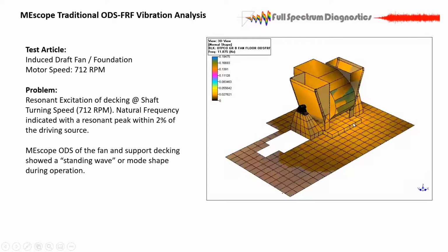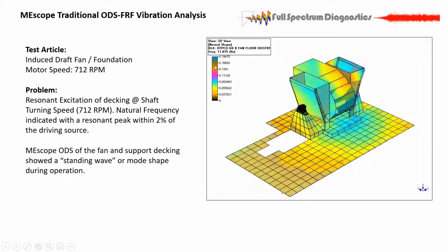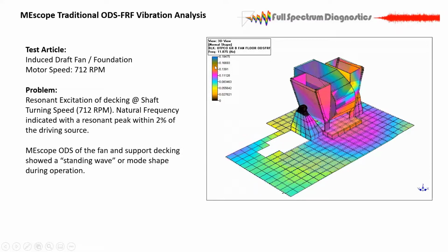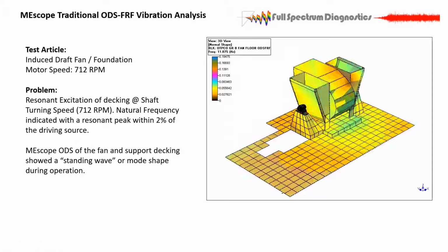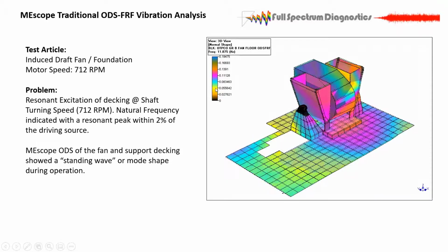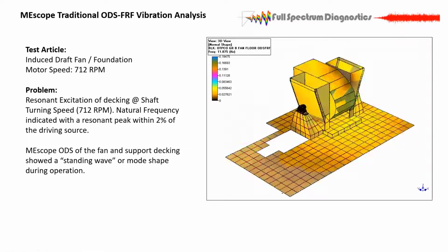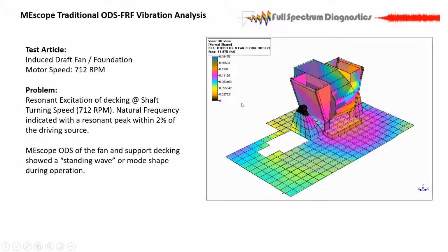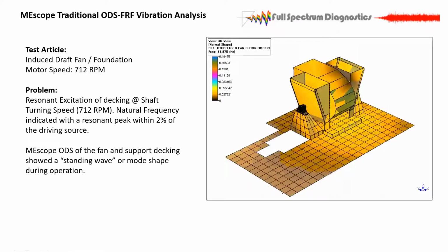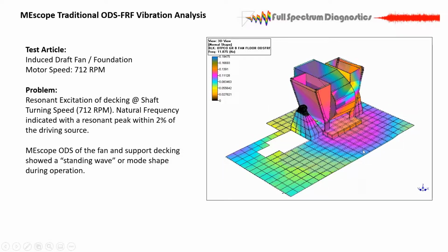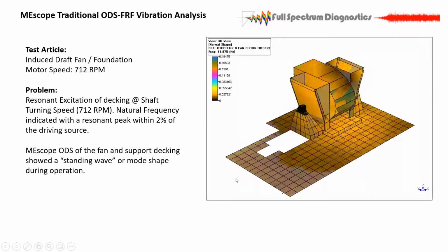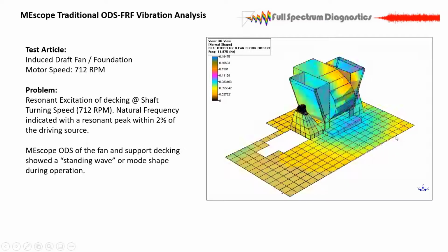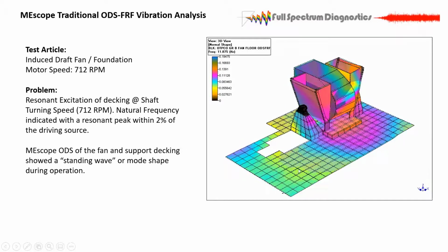So with the color content, it goes kind of in this range, about 0.15 inches per second. 0.05, so something if it was just yellow, that would be acceptable. Anything else above this yellow 0.055 would be extreme for this type of response, especially on a foundation. Okay, so I had to do this with, I think, a 2-foot grid, a couple hundred measurements on the floor, and fairly easy to see what was going on.